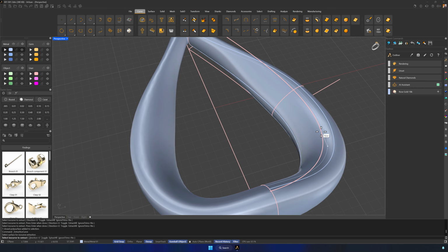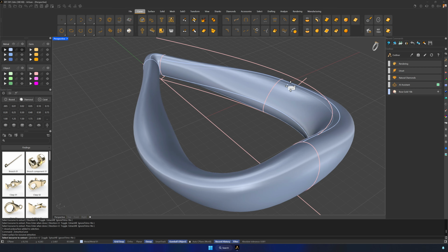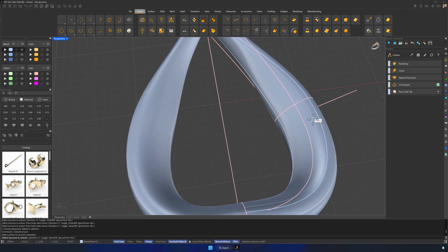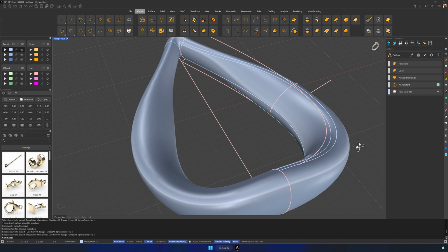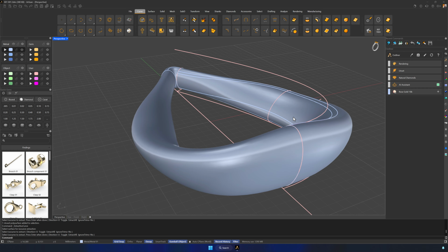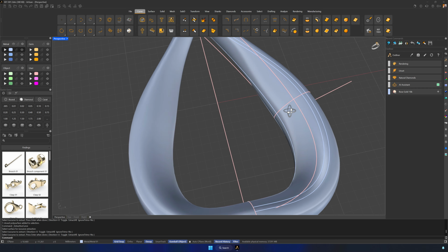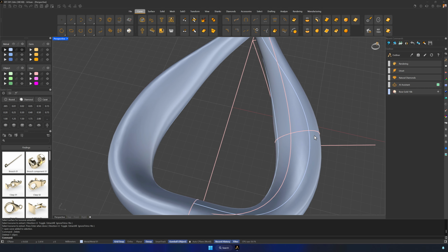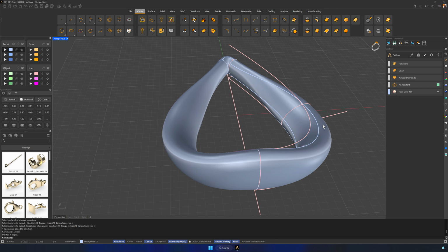If you want to reduce the surface area available for gemstones, simply create another IsoCurve. You can also use the surface lighting as a reference and place a new IsoCurve in the brightest area. After that, delete the previous IsoCurve. Now we have a more defined surface area.